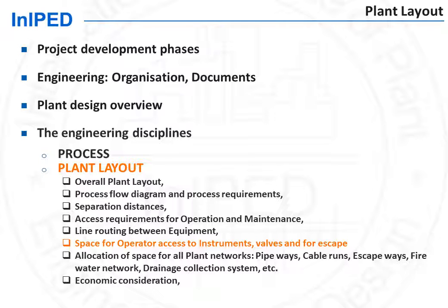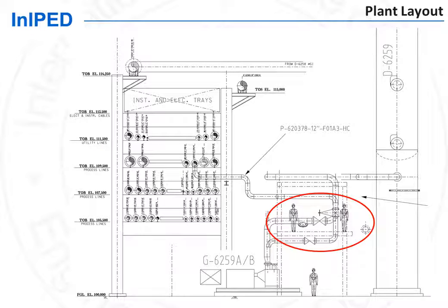Space must be provided for operator to access instruments and valves. For instance, one has to take into account that the operator needs to access the suction and discharge valves on the lines feeding this pump, as well as the strainer and any instruments present on these lines.